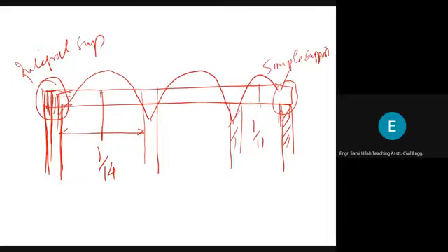And then there will be zero bending moment here because you know that at a simple support or wall, the wall and beam are not integrally connected. So there will be no negative bending moment, and there will be zero bending moment here, and the positive bending moment value will be 1 over 11. And here it will be 1 over 14. And anywhere in between, for all interior spans, the value of positive bending moment will be 1 over 16, times w u l square n.